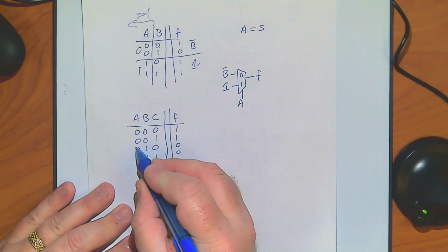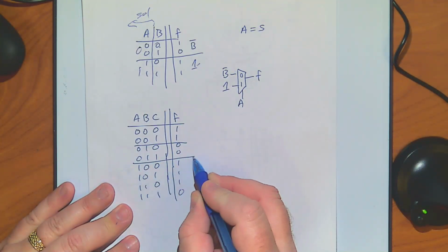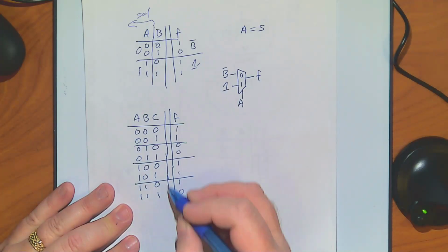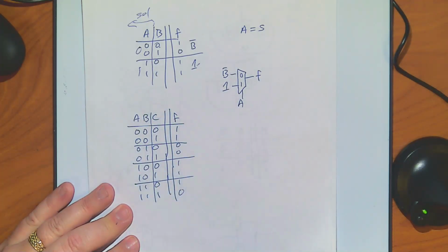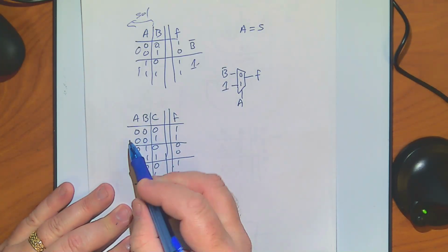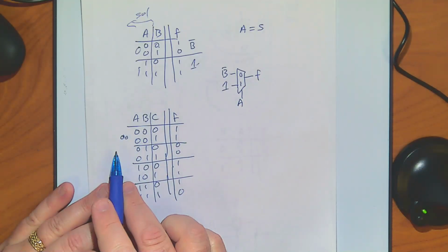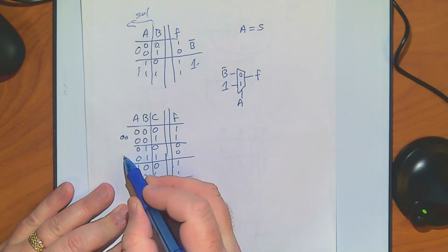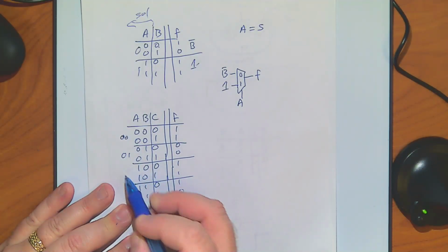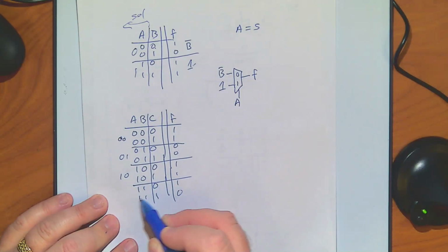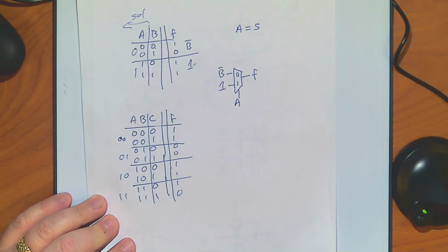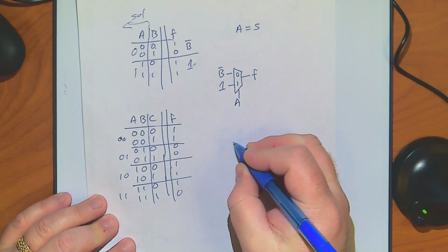Okay, so we're going to follow our thing. We group them up 2 at a time. We cut off the least significant bit. This is now my address, 0 0. It's just a 2-stage. This is just a 4-input mux.